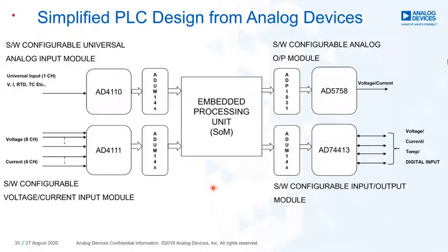Your ADC samples the signal right away at the connector or the point of contact. Then it passes it through SPI, through an isolation barrier. There you have nothing to lose. You already have the 16-bit information there, and the accuracy totally depends upon your ADC's or DAC's accuracy and resolution.